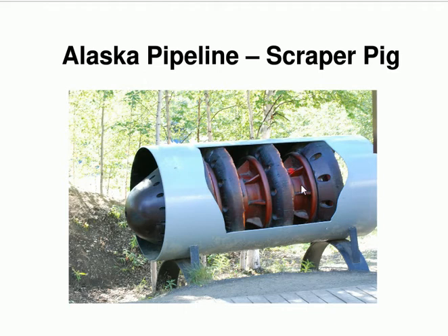And here we get to the cleaning bit. That thing is actually called a scraper pig, little piggy. They stick it in the pipeline, and you can see those things on the side here. They are the cleaning element. So they push some liquid or something behind it, and that scraper pig just moves through the pipeline and tries to scrape off all the dirt and everything else.